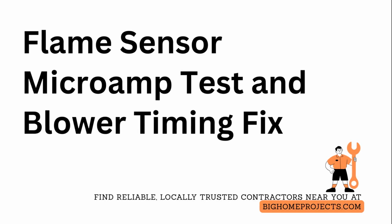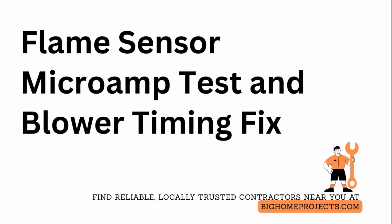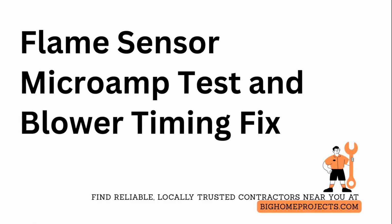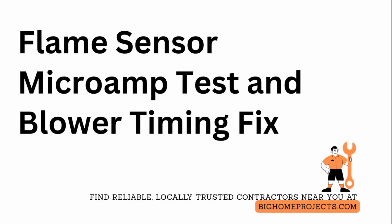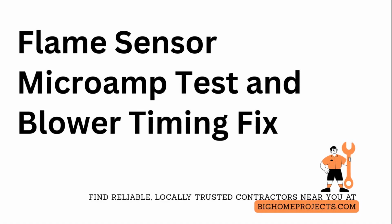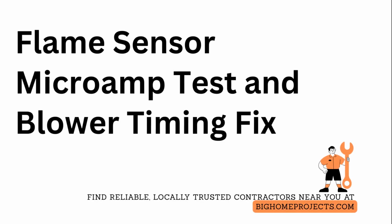Thermostat calls for heat. When the thermostat closes the white call for heat circuit, 24-volt control power from the red R terminal pulses to the white W terminal, and the furnace control board immediately begins the safety and ignition sequence to start combustion and circulate warm air.